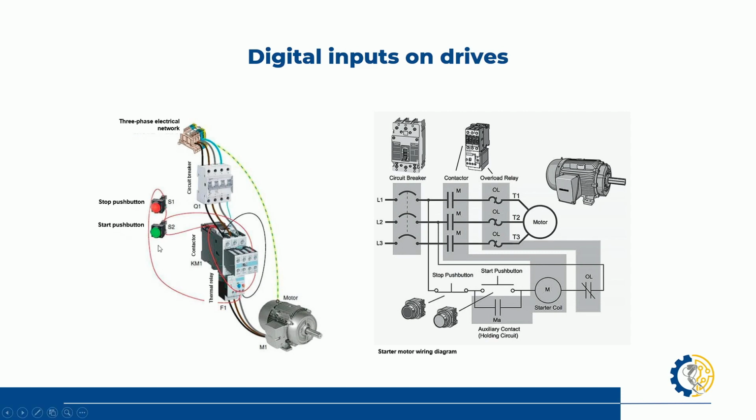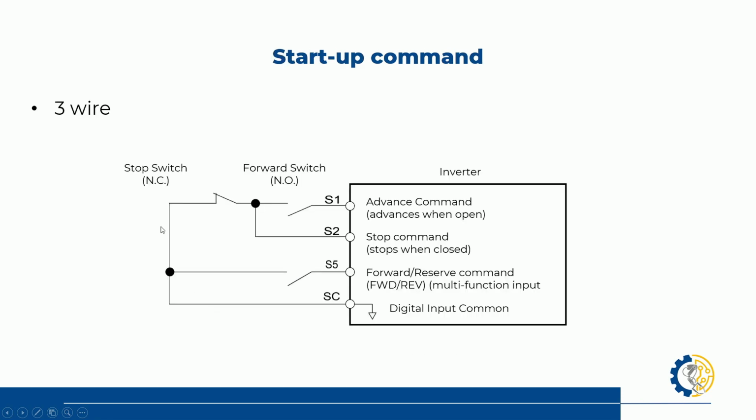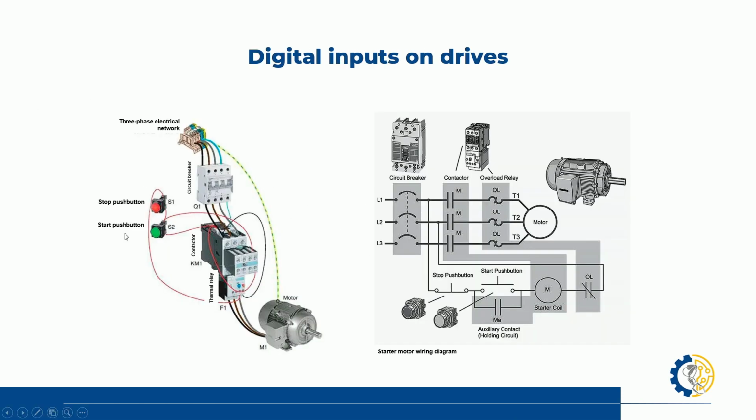And in case this allows it to go through, when we press our stop button, then it is going to unlatch our circuit. And it's going to open everything up so that we don't have anything going to our motor. And so therefore, we have our startup phases, unless we press our start button.